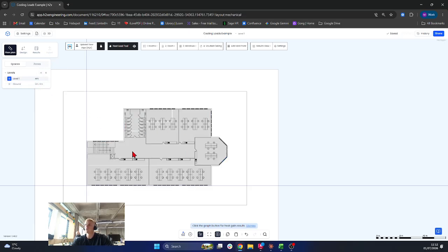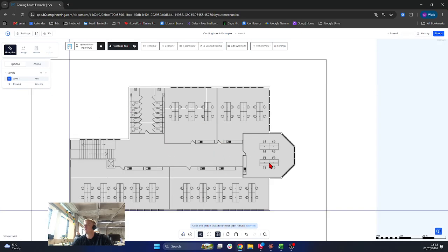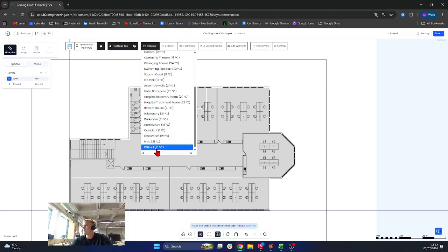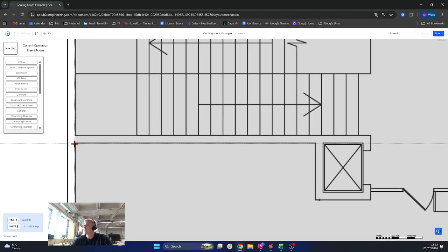Now, if we go up to the first floor, you can see that we're actually going to be shown a grey outline for all of the rooms that we've drawn below. That way, if you're working with sketch information, say like dimensions provided for a given building, you can draw this freehand. Now, if we go into rooms again, we can go ahead and grab another office, left click there to start, bring that round